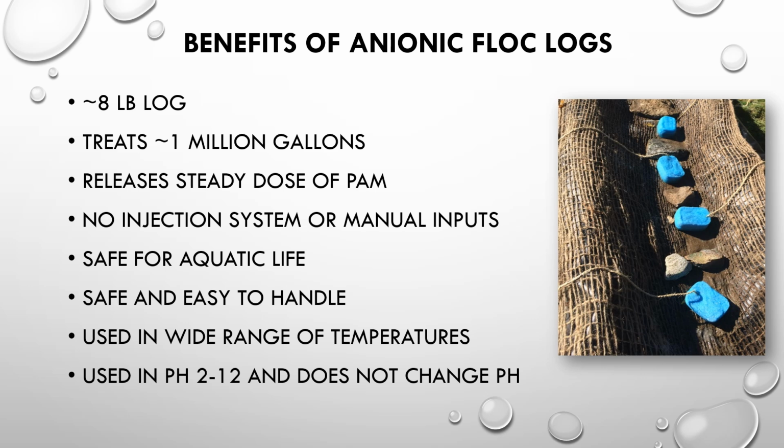You might have heard of things like aluminum sulfate. When that's added to water, it creates sulfuric acid. And if you use too much of it or don't have a lot of alkalinity or buffering capacity in your water, you can kind of crater your pH. So PAM does not do that. PAM is neutral once it's dissolved in water, so it's not pH dependent and it's not going to change the pH. So those are some real benefits of PAM as well, and why we're able to use them in these environmental applications outside of treatment systems where you have to monitor pH or change pH. We don't have to do those things.